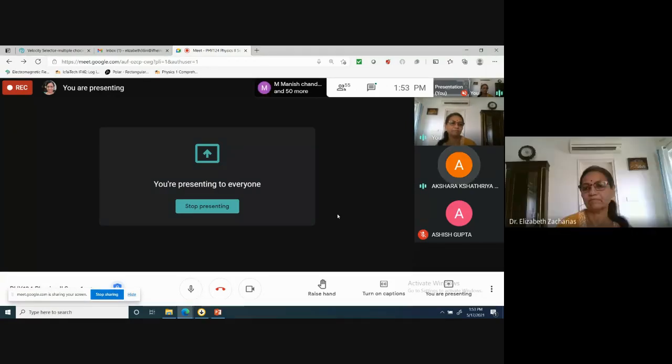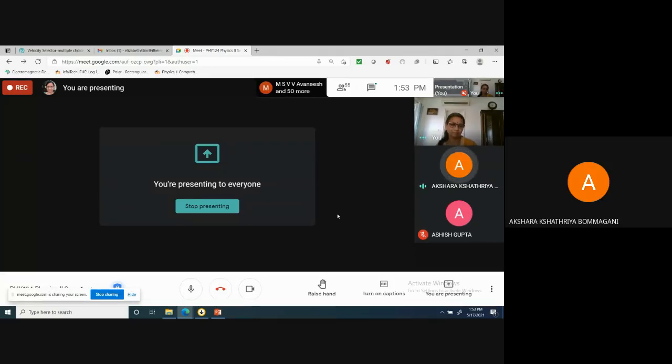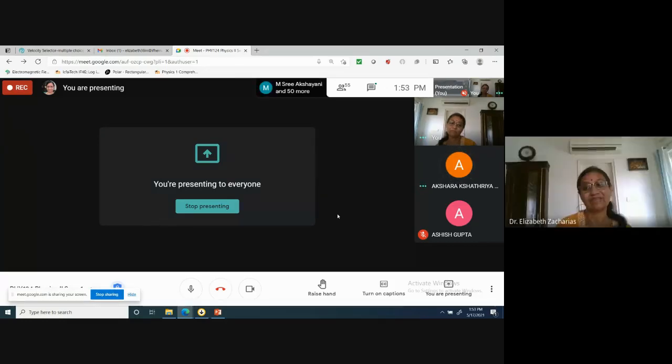We can connect capacitors in series so that the capacitance would decrease and the voltage would be increasing. The capacitance of the individual capacitor will not increase. That will remain the same only. But then the voltage gets shared. The source voltage gets shared. Therefore, your capacitor will not burn out. That's the right answer.